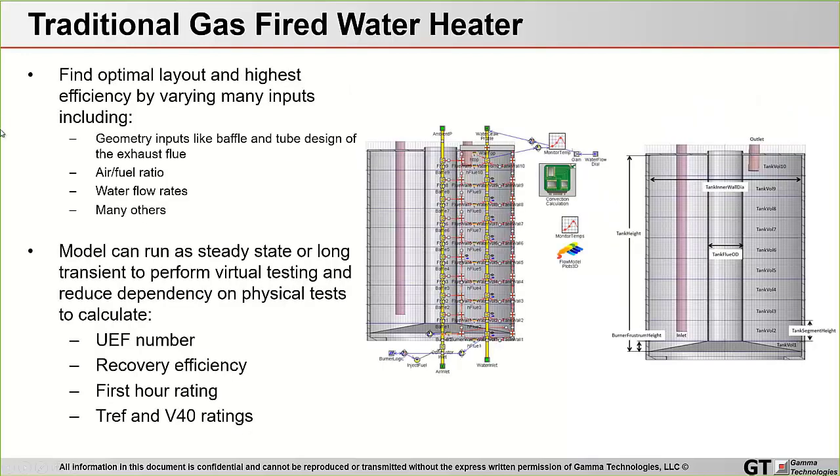Now, if you look at the traditional gas-fired water heater, for example, with a central flue inside the tank, users can study nice inputs, including things like what the baffle design looks like, what the performance looks like with different air-fuel ratios. You can study different water draw patterns and so on. And you can also study these performance metrics like UEF, recovery efficiency, and so on very quickly.